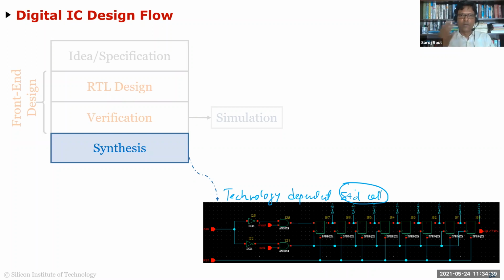So when you want to use a certain technology, let's say I want to use XFAB 0.6 micron technology. So first thing I do is I download what's called the PDK, process design kit, like I was saying. And these cells are part of that process design kit. It will tell you what are the standard cells. And we'll cover standard cells in a great presentation, so he'll cover it in detail next week. And you're going to lay out one standard cell, like the first inverter.